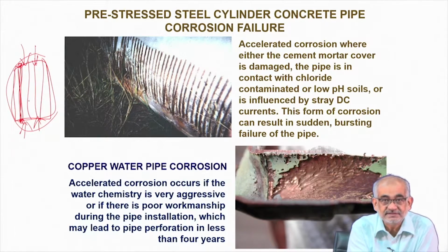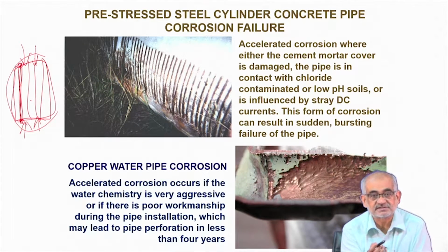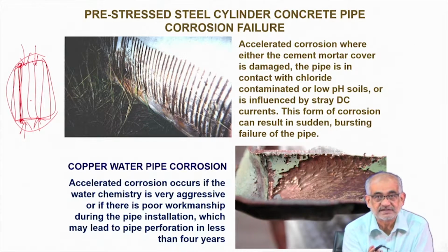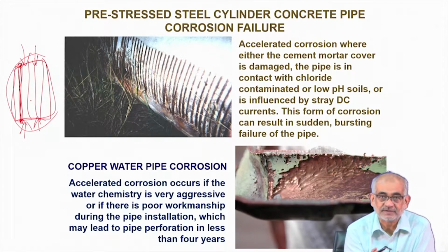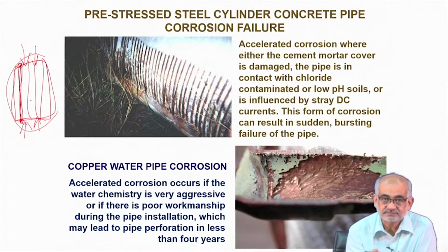But the steel and concrete interface is always a very probable spot for corrosion or damage to occur, because you are crossing over, there will be some amount of gap, and that gap obviously for the structures you can't see from outside, but the length scale of such air gap could be of the order of a few micrometer or even less. Nevertheless, this also is the region where you expect some moisture to be trapped, because for setting the concrete you all the time add water.